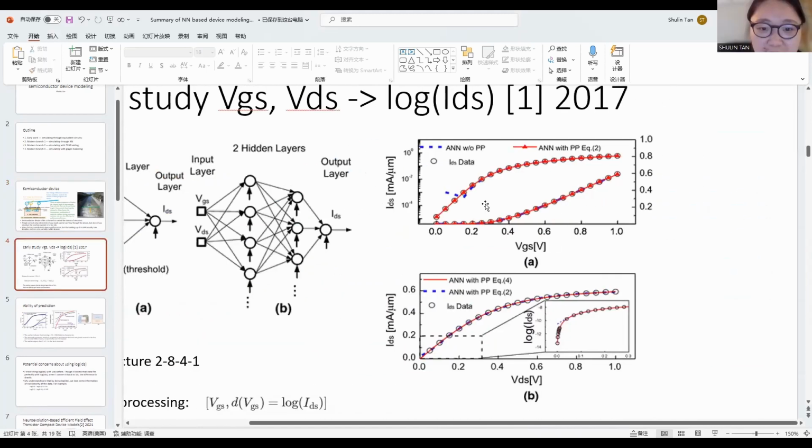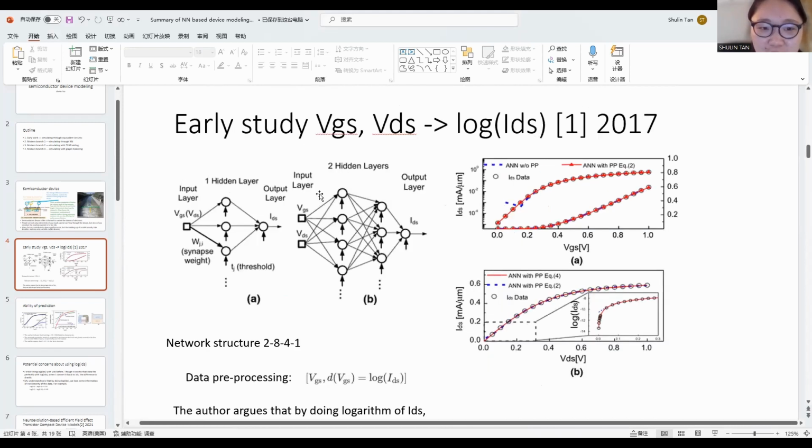That's why you can see the effect of these 2 parameters is actually a huge difference. So VGS affects the current by like 10,000 times, like from 0 to 1, but VDS affects it only from like 0 to 0.6. Okay. So VDS 6 times, and the VGS is kind of like 10,000 times. So that's what I think, it's actually hard for you to build up this one.